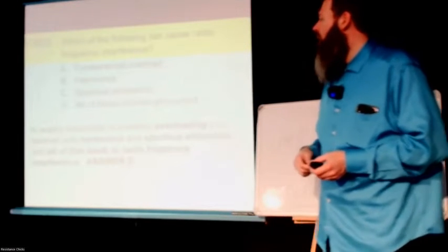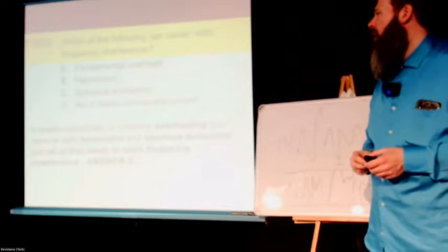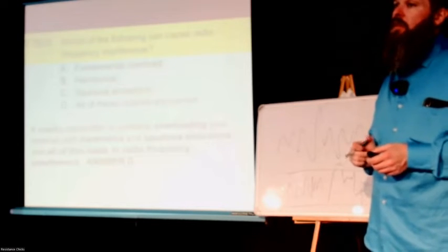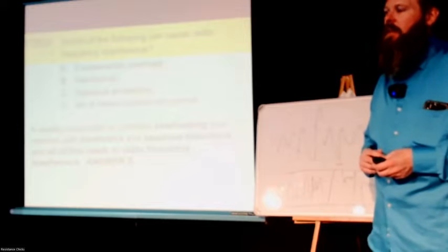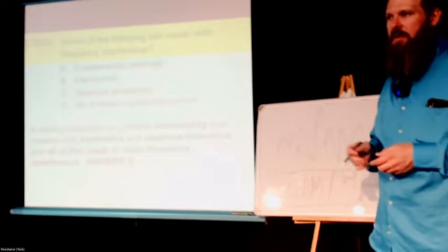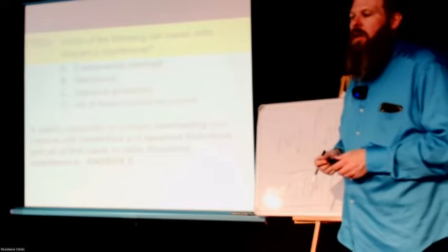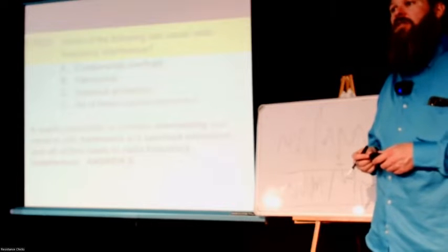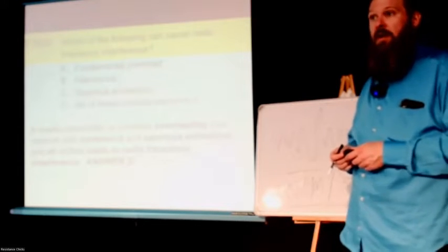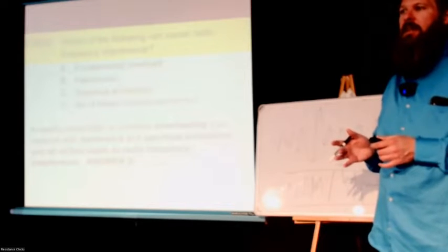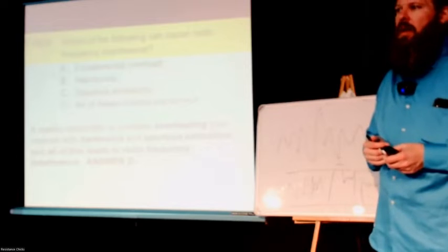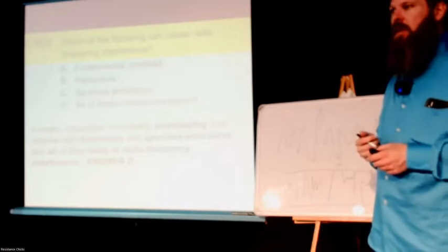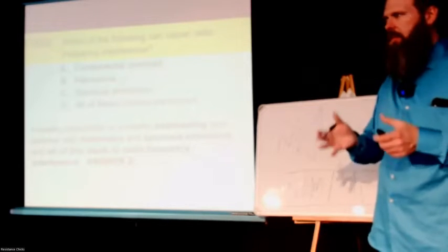Harmonics. So a harmonic is if somebody is transmitting on a frequency that is half of your frequency, their radio will have a harmonic that doubles into yours. Okay, so if you're transmitting on 10 megahertz, I could probably also hear you on 20 megahertz. It will be much weaker, and you're not actually transmitting there because you are actually on 10, but because of something called a harmonic, I can actually hear your signal there, so it can cause interference, even though there's no actual transmitter there.